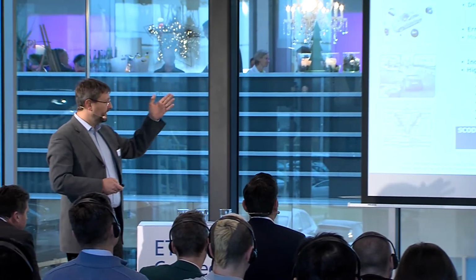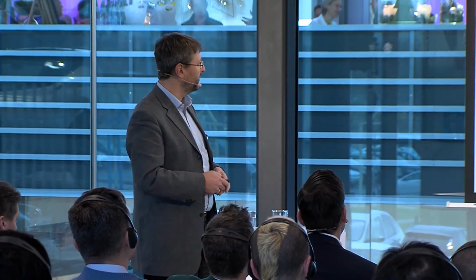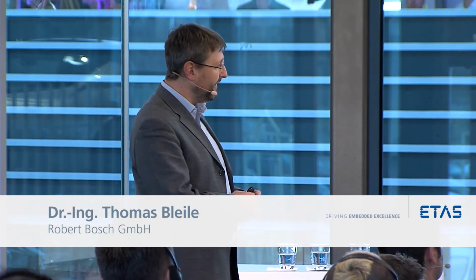Yes, I would like to show you the effect of these methods when they are applied, for example, to an air system of a diesel engine. So it's about filling the combustion chamber with the right amount of fuel and air, and we've got the throttle available for that and the intake valve. And we looked at the equations and how we can model this. And the function that was the result is depicted on the right-hand side.